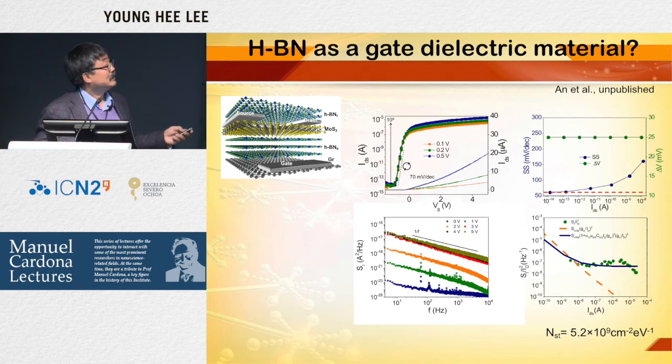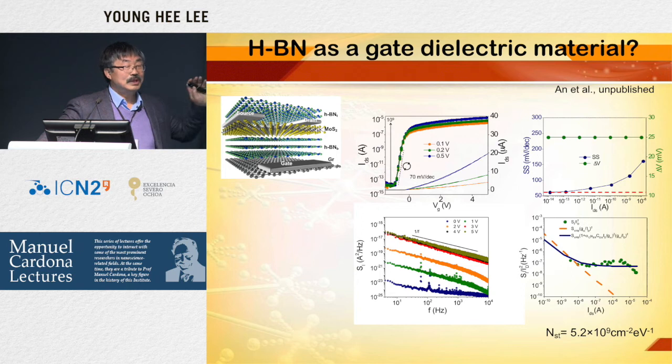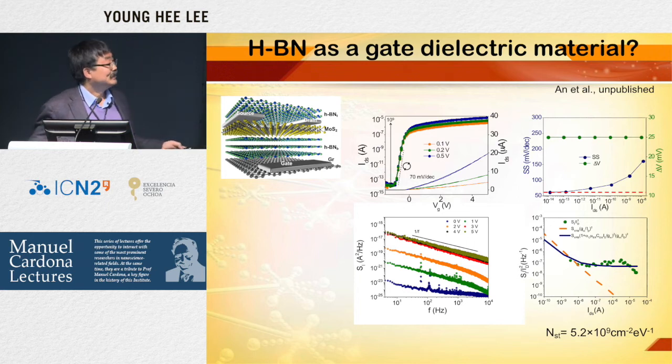And if you look at this very bottom, we have here like a 63 millivolt, which is very close to the fundamental limit. And one reason that we have this really very ideal number is because of this low trap density, which is inherent from this hBN. hBN is a really flat substrate that provides no trap charges. There is still some, okay? It's not 100%, which is caused by the transfer. But this 10 to the 9 value actually is 1,000 times smaller than that of silicon oxide substrate. So this significant reduction of this trap density definitely improves the subthreshold swing.